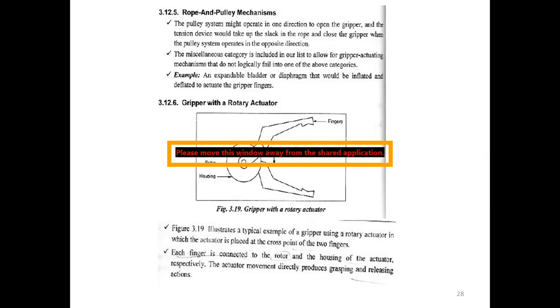So how does this work? The pulley is a simple machine which consists of a rope and a grooved wheel. The rope fits into the groove in the wheel, and pulling on the rope turns the wheel. Pulleys are generally used to lift objects, especially heavy objects. The object lifted by a pulley is called the load. Usually we attach the rope first to the bottom of the pulley, then loop the rope down to the wheel on the movable pulley. Now we loop the rope back up to the top fixed pulley. Make sure that the rope is fully fitted into the grooves.